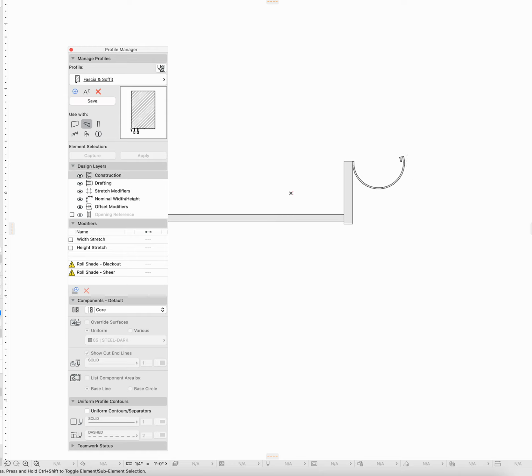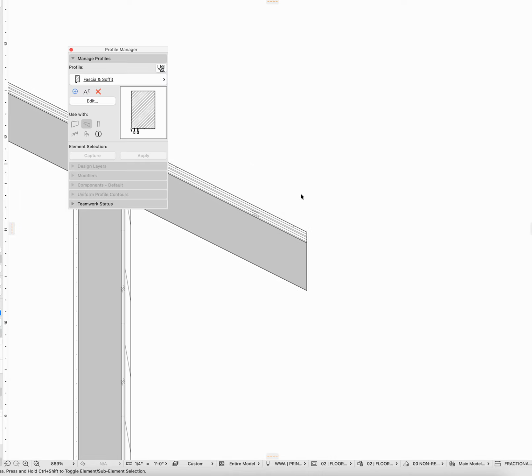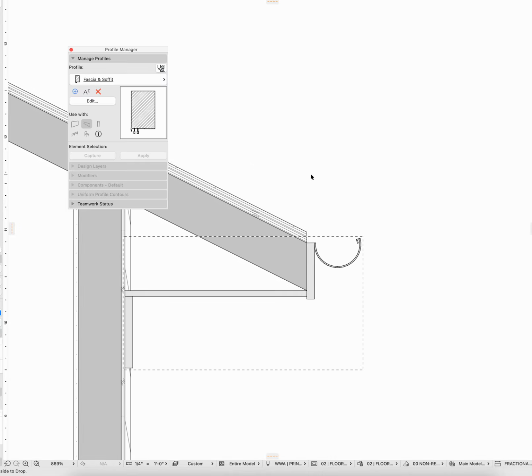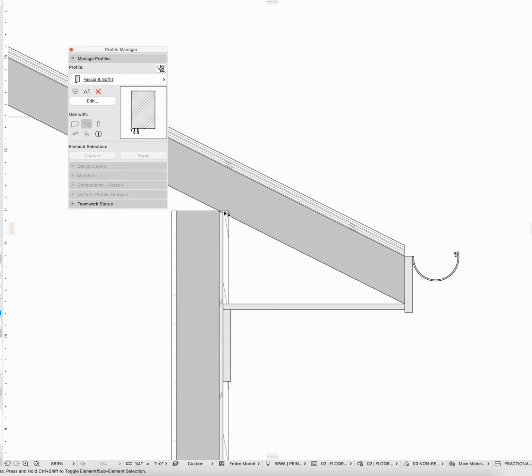Center of current view. Let's go back to that section because I do actually want to also be able to draw this in relatively quickly. So what I'm going to do here actually is take a hotspot. Just realizing that my whole work environment's cropped off here. Take a hotspot and I'm going to drop that in at the top of the stud right here. That's where it's going to line up. So now if I grab all this stuff and cut it, including that hotspot,